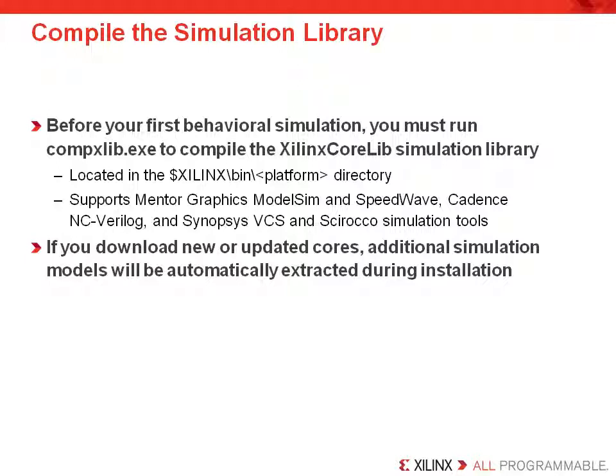Remember to analyze the wrapper files for your cores before you analyze the file that references them. Also, if you are using a simulator that is not supported by the compxlib.exe script, refer to the code generator guide and your simulator documentation for information on how to compile the Xilinx CORE Generator library.